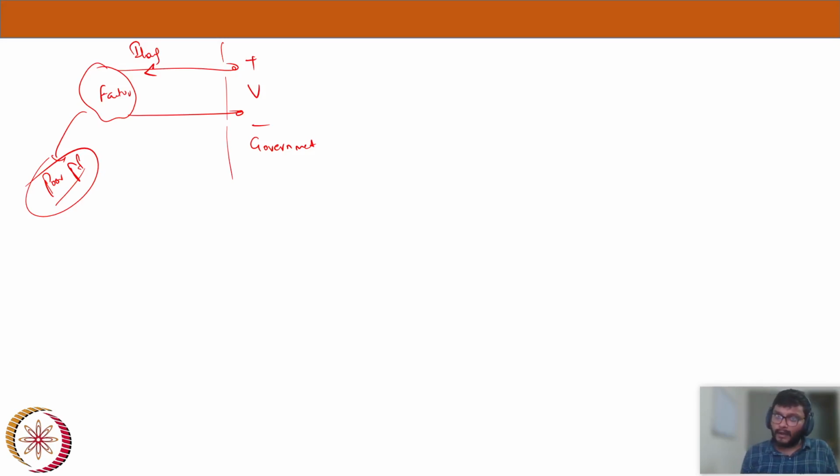So factories need to improve their power factor. In that application, this synchronous motor concept is very, very useful. And just now we also discussed, if you can operate your synchronous motor in the over-excited condition, you will definitely draw a leading power factor current.